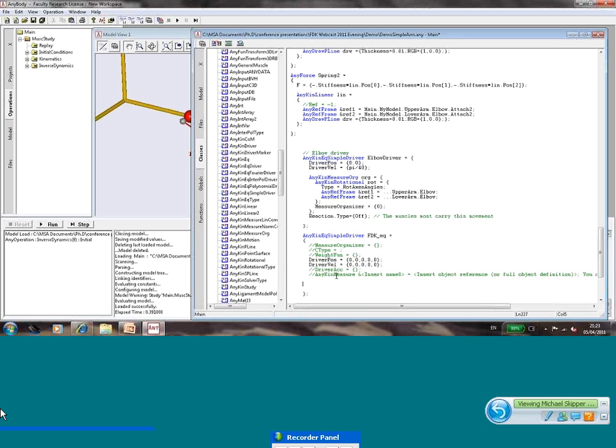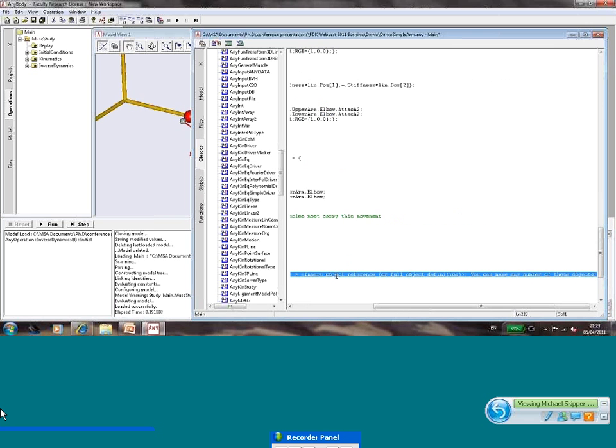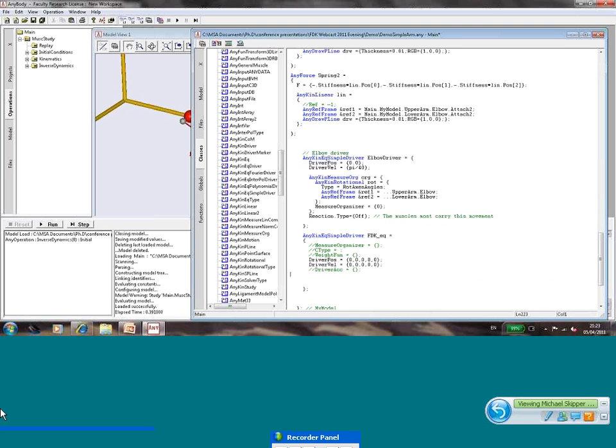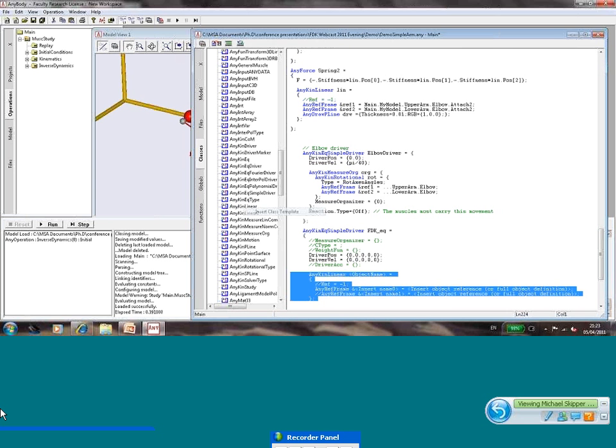So what we then need to tell is which degrees of freedom within the system these force-dependent directions should correspond to. And what we want is the translational coordinates of the center of the Revolute joint from before, and then the rotation within the Revolute joint from before. So these 5 degrees of freedom. So we'll put in a linear, which will tell us the free translational component, I'll call it linear. And then I will again need to put in the references to that point.